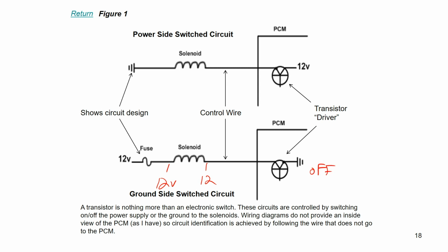What we're going to see with this circuit on, or even stuck on, is 12 on this side and 0 on this side. That would be what a stuck on solenoid would look like. If that driver was on all the time, that's what I would see, 12 and 0. So the 2 is never even an option for the driver being on all the time. And that's a standard piece you want to remember moving forward for any circuit like that.